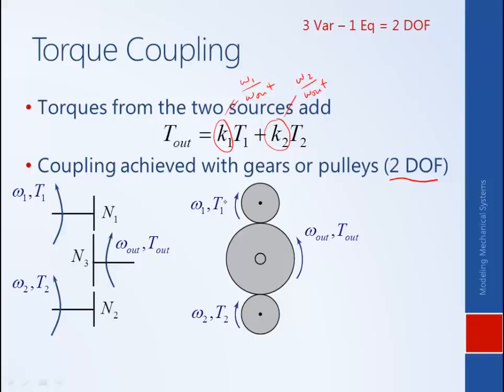And so those 2 degrees of inputs are free. But once we set T1 and T2, the IC engine torque and the electric motor torque, then the output torque is defined. So we don't have control over that. So that is how we come to the definition of this as being a 2 degree of freedom system.